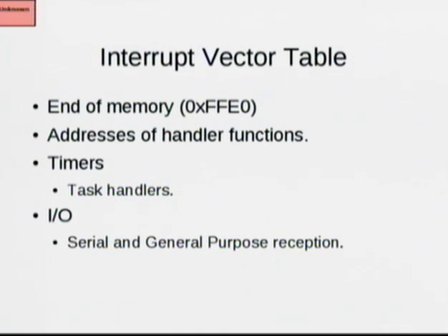You can also look at the interrupt table, because in the same way that there is a standard word at which you write all of your outgoing bytes, there's a standard address at which the hardware looks to figure out where to jump when an incoming byte arrives. And you can run through this list, and everything has a meaning by hardware, so you know that it will apply to your firmware image.